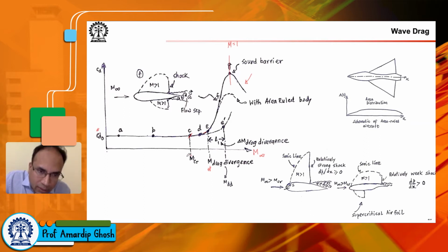So you can see that the critical Mach number of a wing is an important parameter, because the drag divergence Mach number closely follows the critical Mach number. If you have somehow reached critical Mach number, it is very likely that a small further acceleration of the vehicle can lead you to this drag divergence Mach number, in which the drag on the vehicle can increase rapidly and significantly.